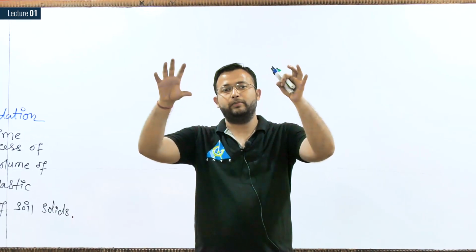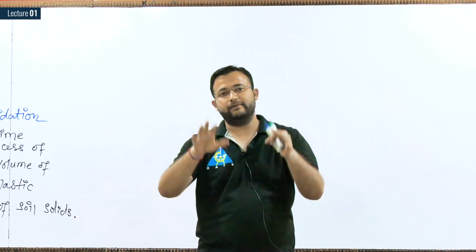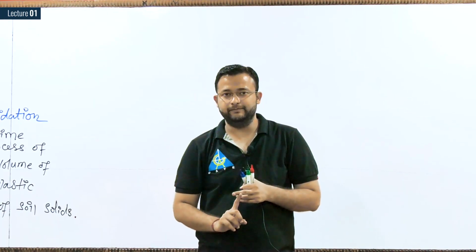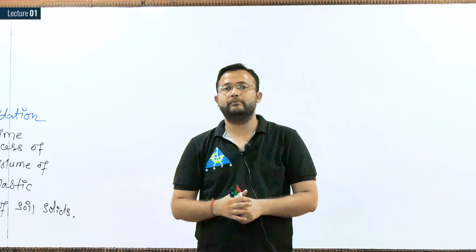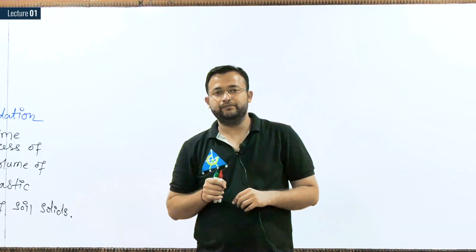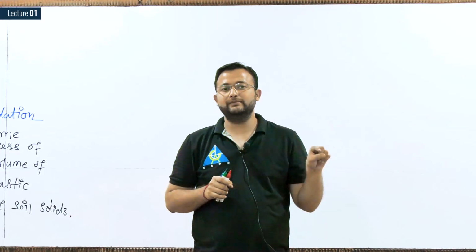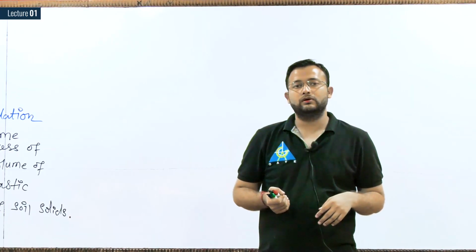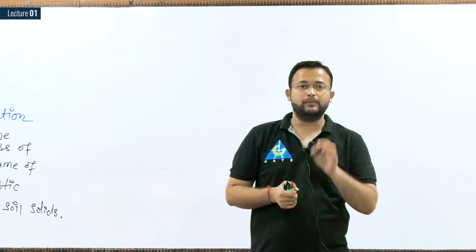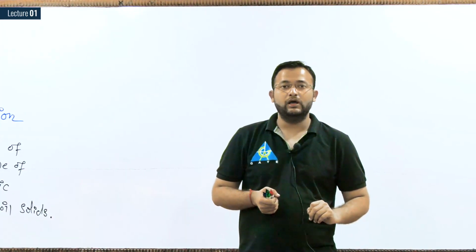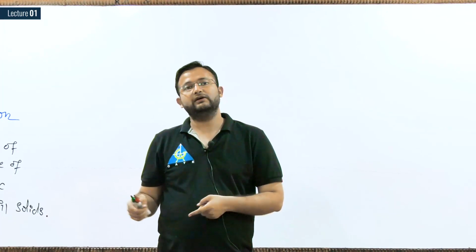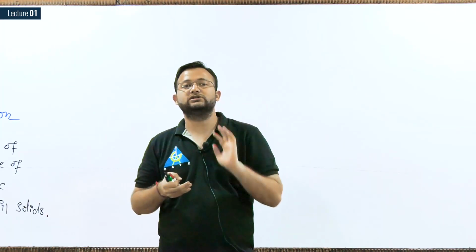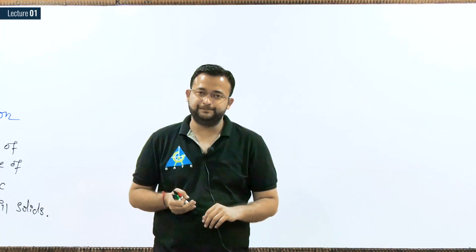Compressibility means it is the property of the material. If we apply the load, the material volume will reduce. That is called compressibility. The compressibility may occur because of air, because of water. If we are reducing the volume of soil and removing the air, the process we call compaction. If water is present in the soil and we are applying the load and removing water from the soil, the process we call consolidation.